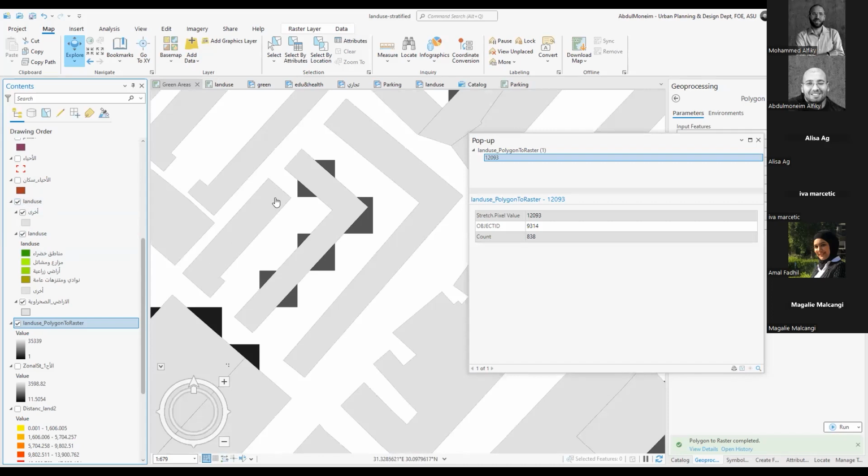This one, this guy, didn't rasterize because the size of the pixels was too big. If I made it 5 by 5 or something like that, this one would show. So you have to take care when you're rasterizing that rasterizing simplifies the data, and the simplification should have a limit to it.